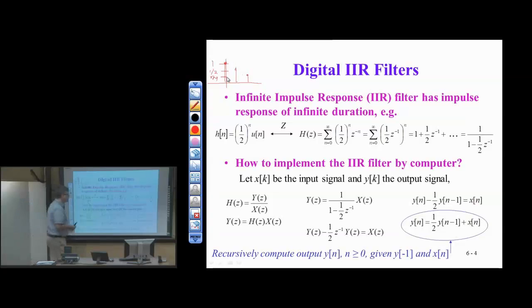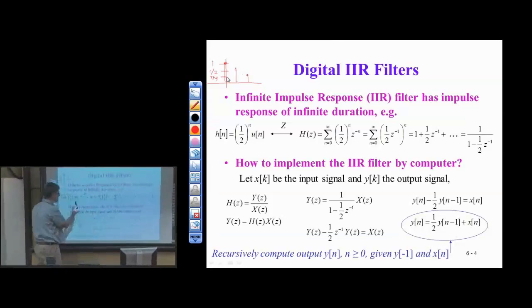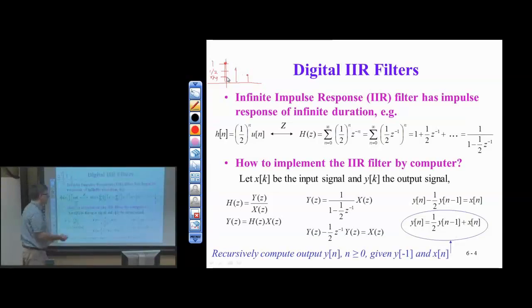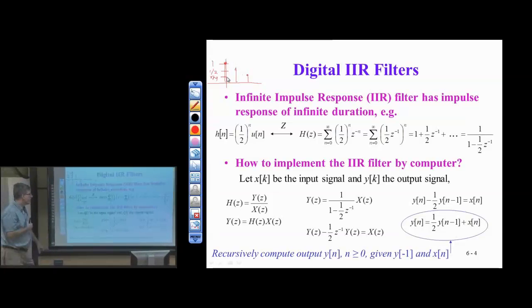If we were to take the z-transform, put the signal directly into the z-transform formula, we sum over n from minus infinity to infinity, but because we multiply by the step function, we only have to sum from 0 to infinity inclusive. We don't have to start back at minus infinity. The values of h of n are 0 for n less than 0.